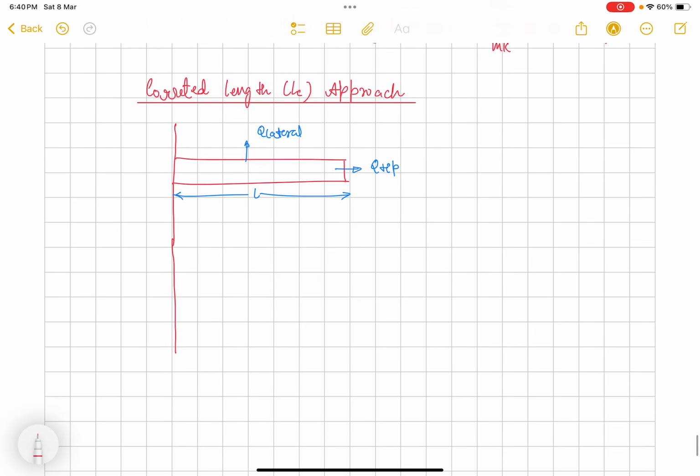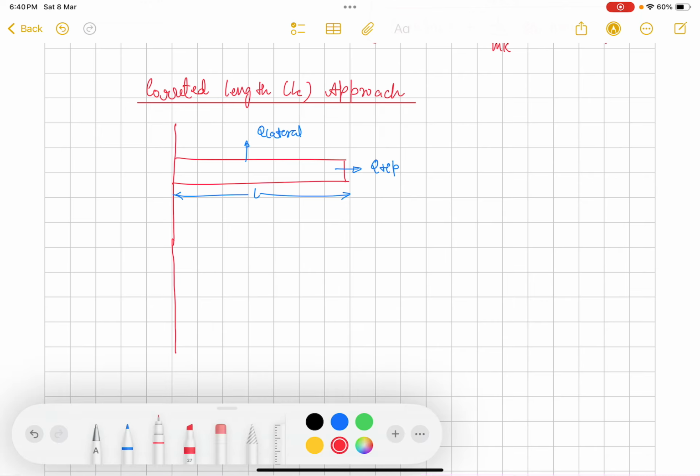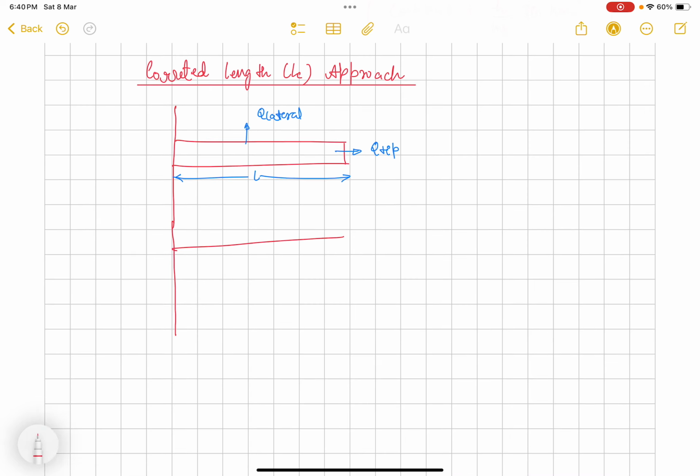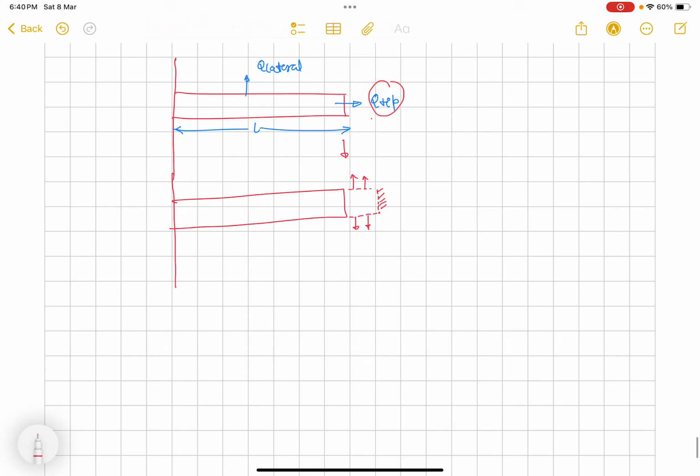so to model the heat transfer from the tip, the philosophy is that add extra material to this fin in the longitudinal direction, which will contribute to the same heat transfer as that of the heat transfer from the tip, but keep the tip adiabatic. Alright, so how much should we add to this length?